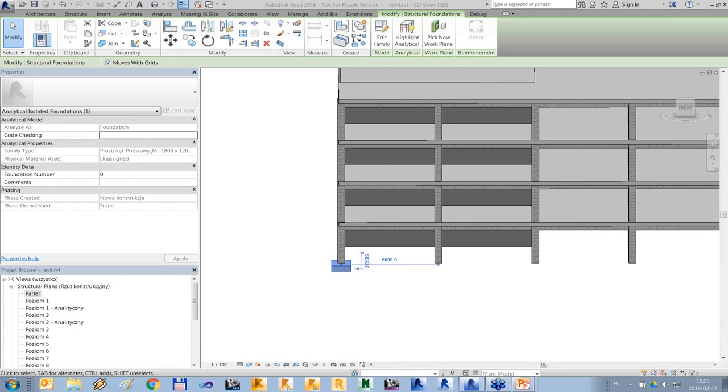So you can save, for example, a Revit file in another location with another name, and you transfer it already into Robot. So the transfer is kept in the meaning of the direct transfer, because if you use the transfer by file, it doesn't matter whether it's exactly a 100% pair of files. But in case of direct import or direct export, direct integration, both files must be opened simultaneously in both programs at the same time.